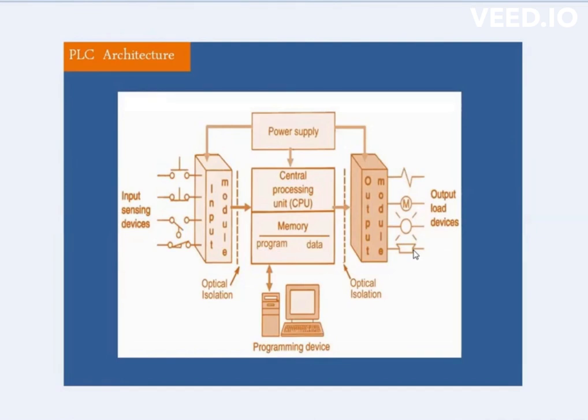It acts as a bridge which is connecting our input and output devices with the CPU. It is used to give the communication between I/O devices. That means field instruments like push buttons, switches, transmitters, control valve, solenoid valve, VFD. So these are all the field instruments, and it is making a bridge between those field instruments and the CPU.